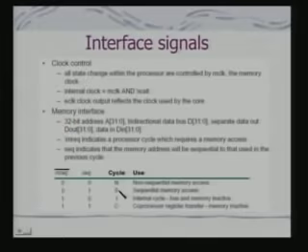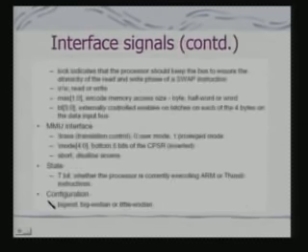And the cycles which are defined, you will find non-sequential memory access, sequential memory access, internal cycle. In an internal cycle, bus and memory are inactive, so the bus can now be used by some other bus controller. Then this is co-processor register transfer. So now the data transfer is to the co-processor register and not to the memory locations. So these are the bus status signals which are provided by the ARM7.